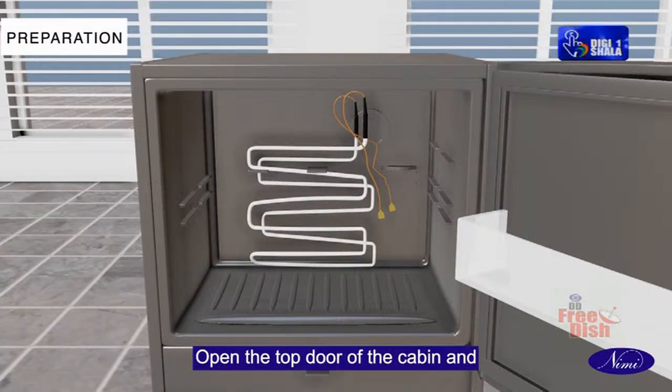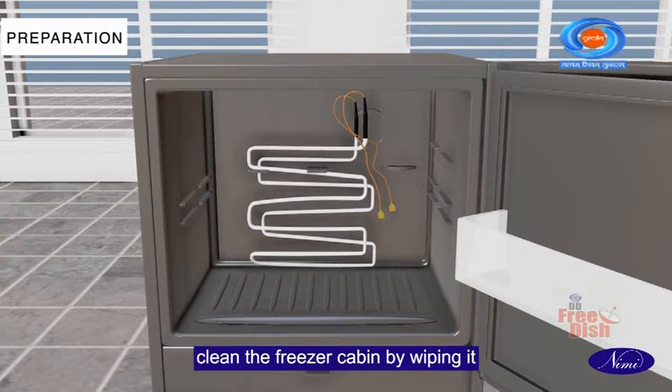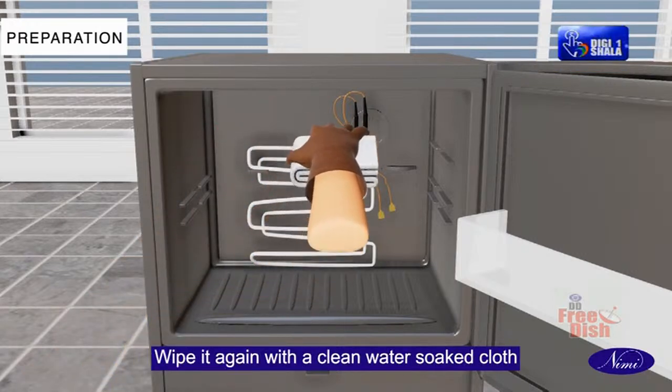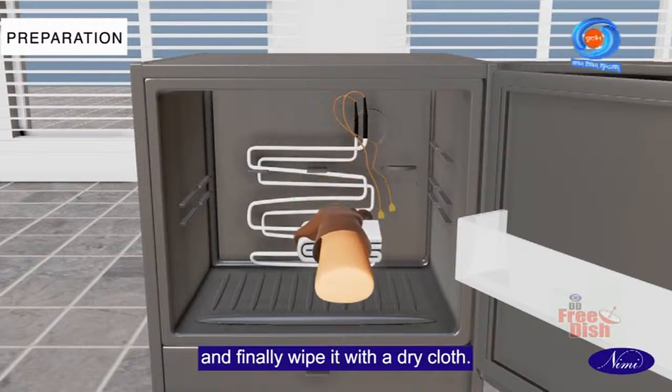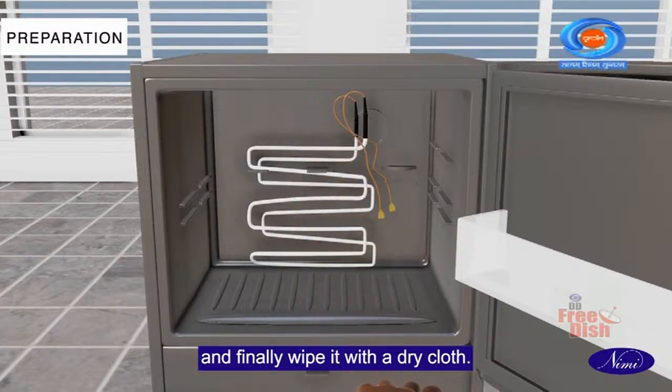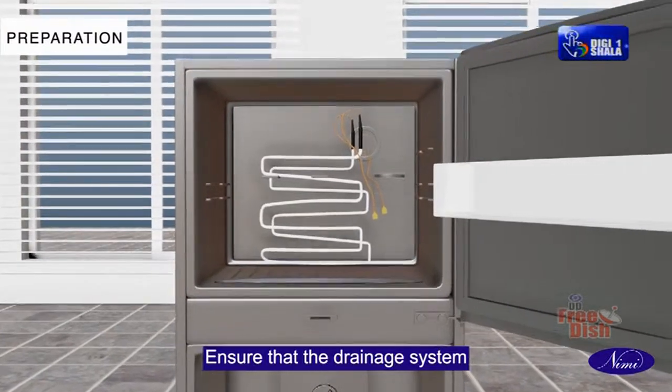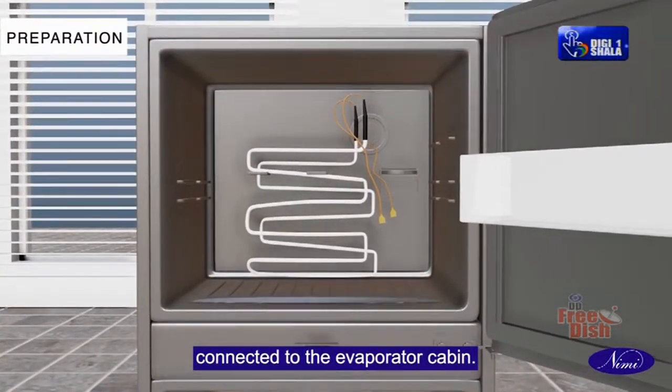Open the top door of the cabin and clean the freezer cabin by wiping it with a mild detergent solution soaked cloth. Wipe it again with a clean water soaked cloth and finally wipe it with a dry cloth. Ensure that the drainage system is connected to the evaporator cabin.